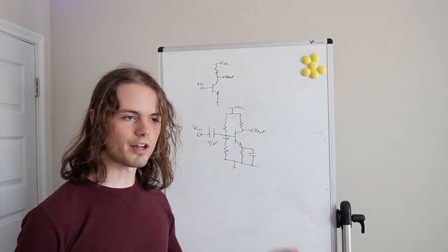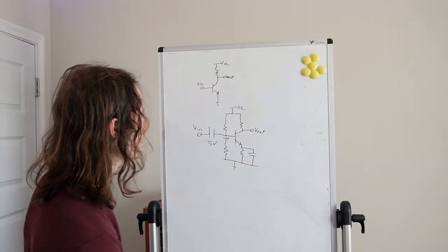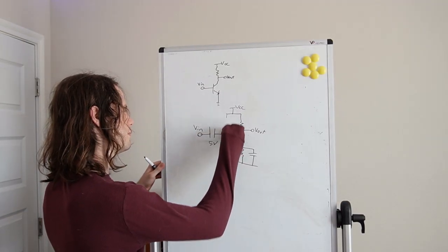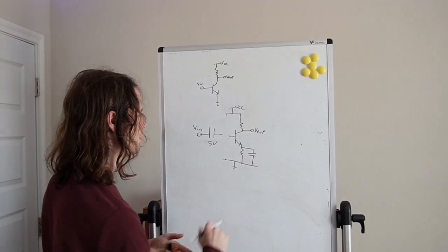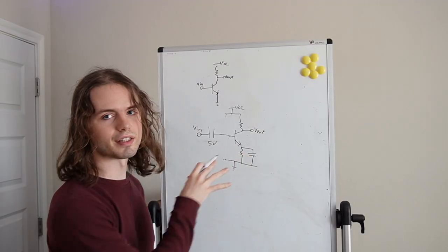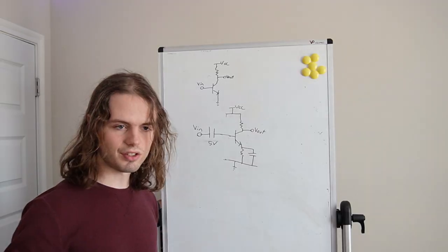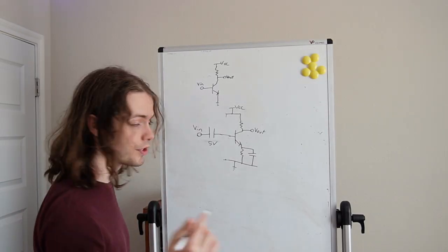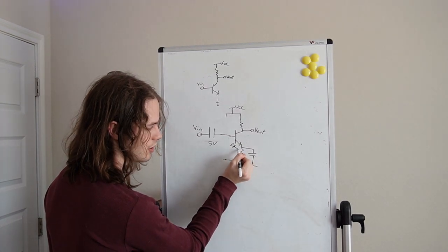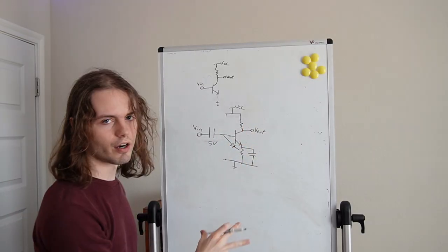With the capacitor part out of the way, let's move on to the next part, which is these two resistors here. So the first thing I'm going to do is actually remove them. Let's say you feed your signal directly into the BJT. Well, since we have this capacitor here, it's going to be an AC signal centered around 0, which is a problem because for a BJT, there's a minimum voltage here, which essentially acts like a diode, before the rest of the amplifier will conduct.